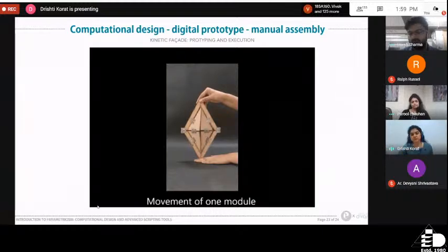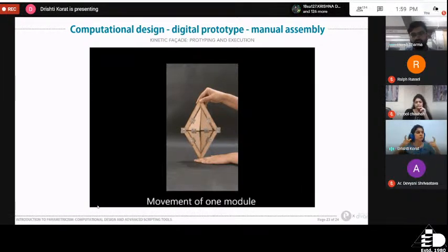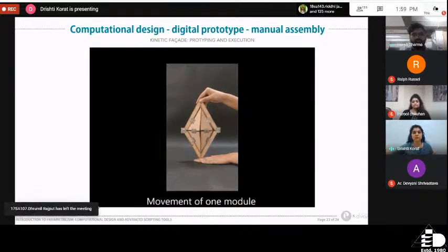But when we look at generative design, which I talked about, where we're actually tapping into the potential of a computer, it is a process where the computer itself will change all the dimensions and evaluate. For example, say I have a rectangular chaja of 2 meters by 4 meters in length, and those are my parameters. When I do it manually, I will check half a meter, 1 meter, 2 meter, 4 meter. I will manually try to change the dimension and see what the effects are on the final analysis.